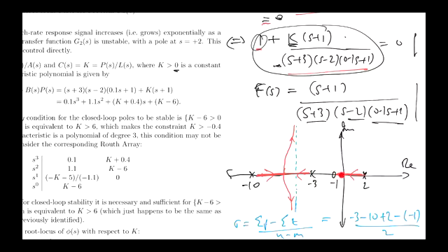That closed loop pole will never decay faster than e to the minus t, because it gets blocked by this zero. Okay? These ones are always in the left half plane, so they're not going to cause any problems. But we need to bring this one in to the left half plane to get closed loop stability.